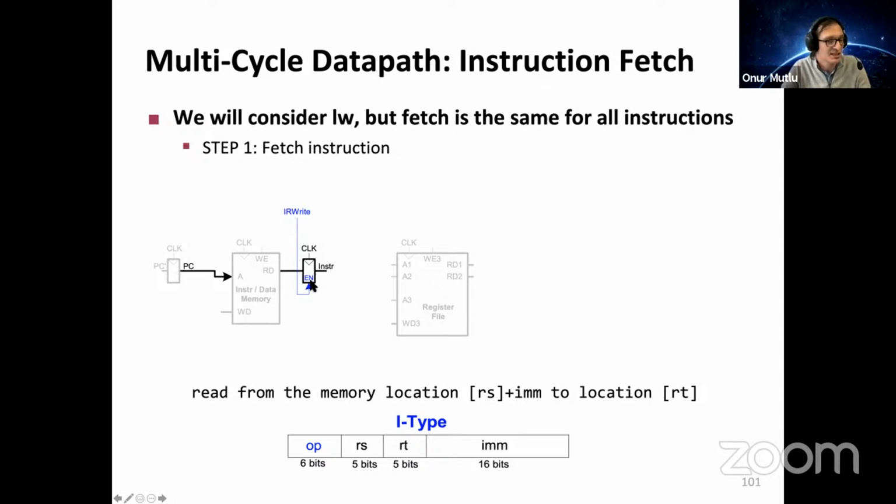We're going to latch it into a register. Why? Because this is our clock cycle. We want the clock cycle to be no longer than this, let's say. Now we latch it. We don't need to do anything else for this instruction. Now the instruction is going to be processed in the next cycle, be decoded, and read the register file in the next cycle.